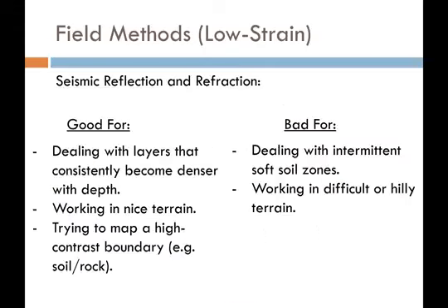So let's talk a little bit and differentiate between seismic reflection and seismic refraction. What are they good for? Well, they're definitely good for dealing with layers that consistently become denser with depth. So if we have a soil layer system where the soil layers are getting denser and denser as we go down, these methods are going to be great.